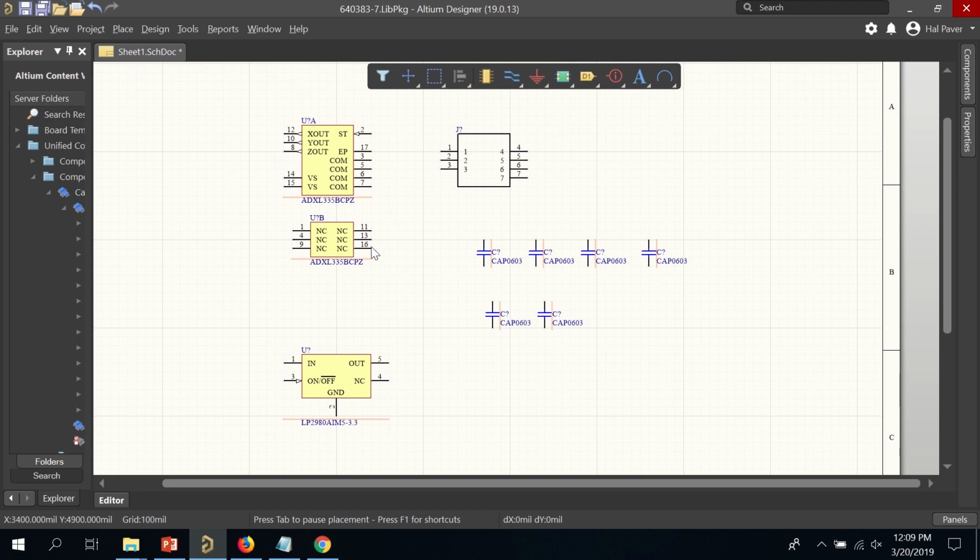So how do I hook up my components to one another to designate what electrical connections I'm hoping to make? So you can use this bus bar. It's a place wire. You can hit Control W or click this icon. We're going to start by laying out our grounds.